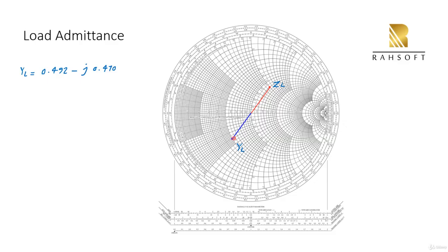What I suggest is printing a Smith chart on paper, and then you can use a ruler and pen to do this. You're going to get exactly this value. But in this picture, you can see something close to 0.5, though this is not very precise. I'm just showing you the method. The best way to do this is using a hard copy. You can just print it on paper, and you're going to get very precise results.